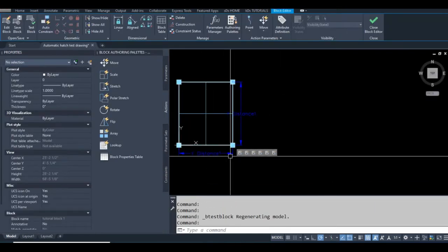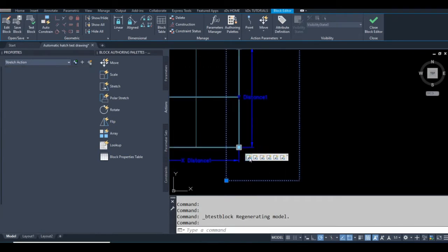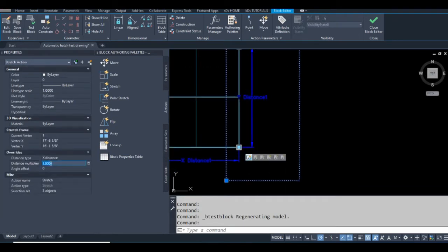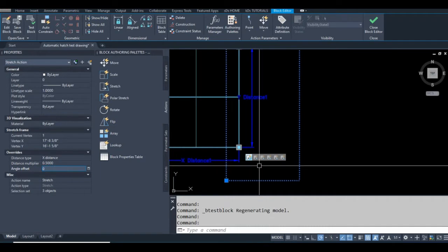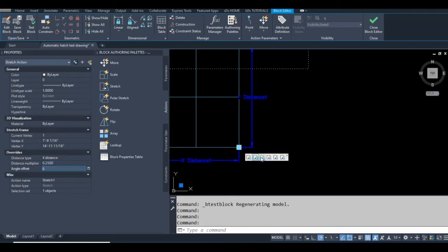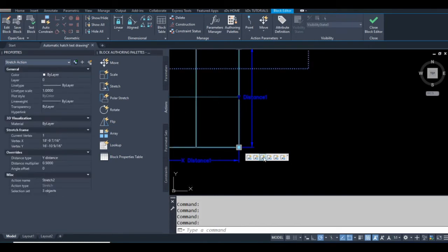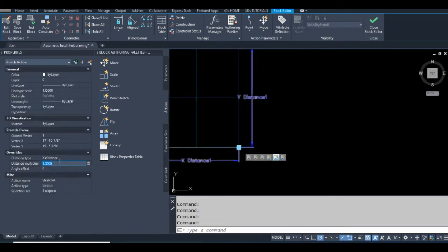So once you add additional stretch actions, you actually have to take these and halve them, because you have two stretch actions pulling in one direction at the same time. So you can see why there isn't three grips. That would become really, really confusing. It'd create really erratic results, I guess.